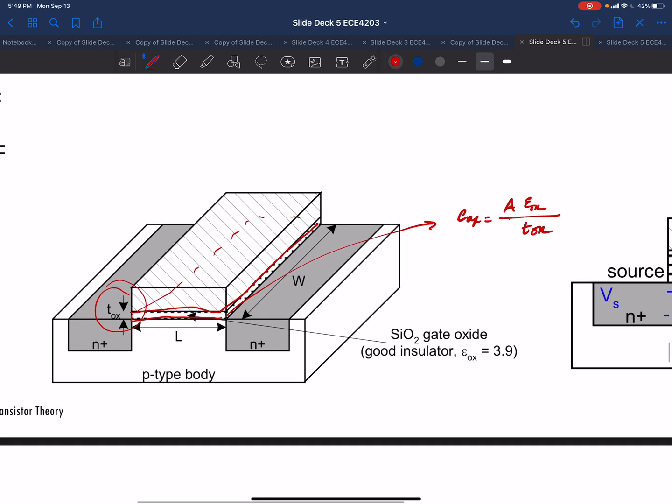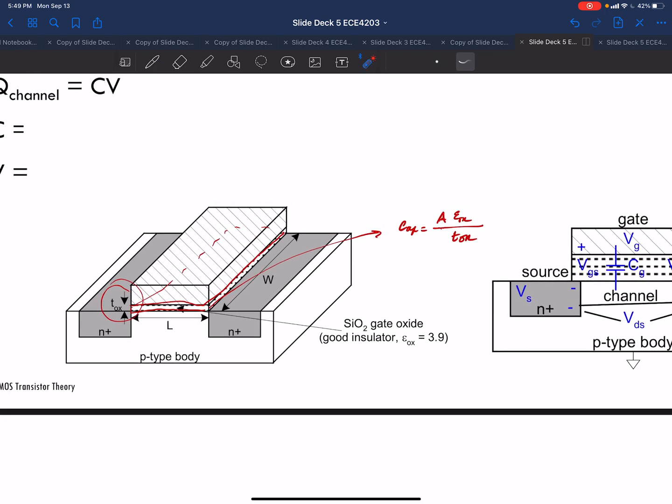Now, when we draw a transistor from the side, we look at the source and the drain, and the polysilicon gate. The geometry of the channel is the separation between the source and the drain, which is known as the length. We usually don't look at what happens in this direction, but you can adjust it, and that is called the width, which is how long the source and the drain run along the gate.